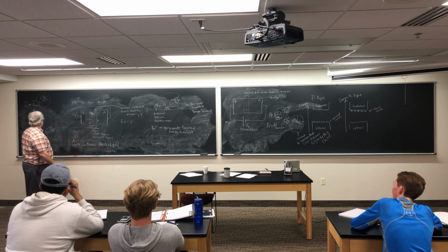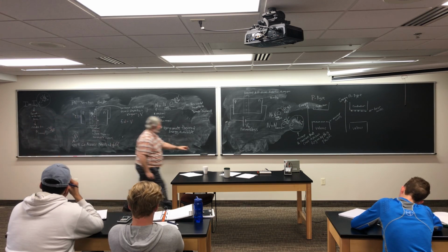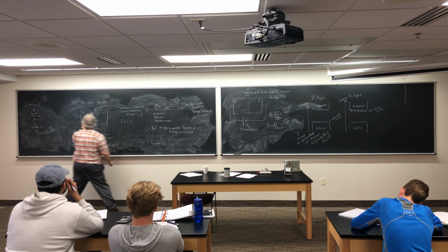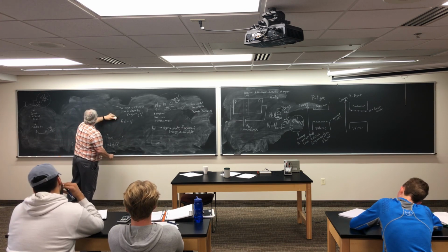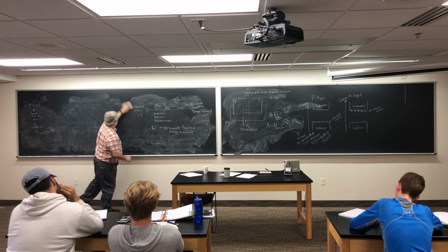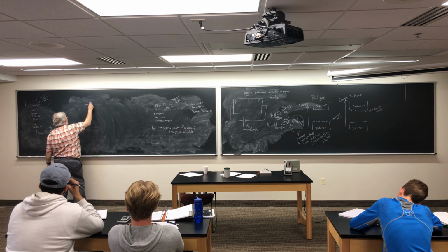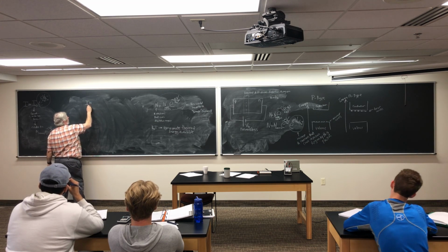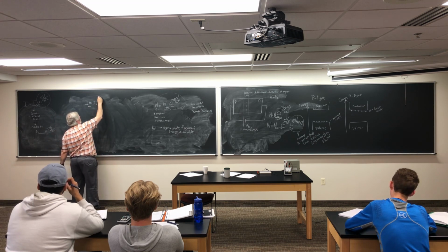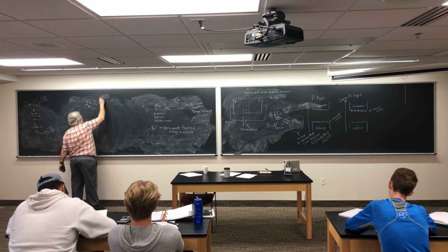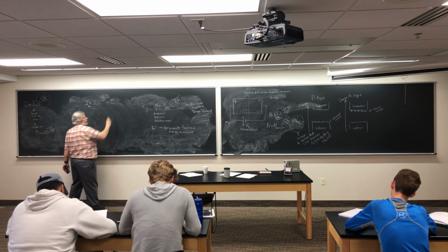So what we do is we make the total current look like this. They do a more detailed analysis than what we're doing. We're just making arguments about this. Say the total current is some sort of this base current times e to the bias voltage over kT minus the probability it might just jump back too.